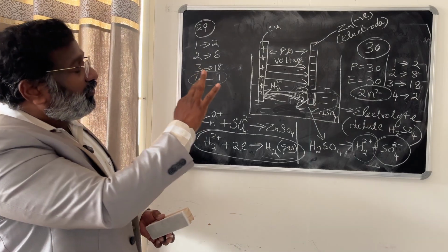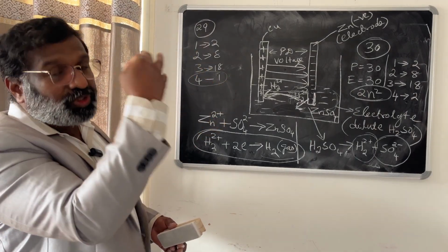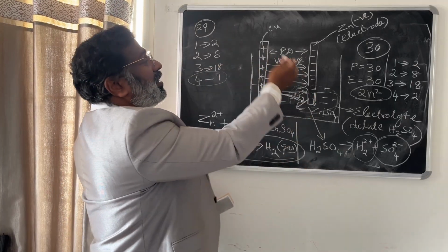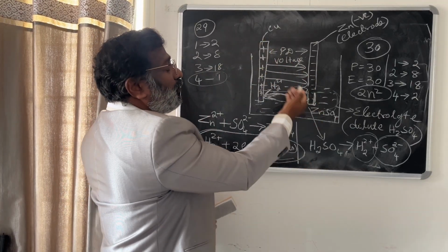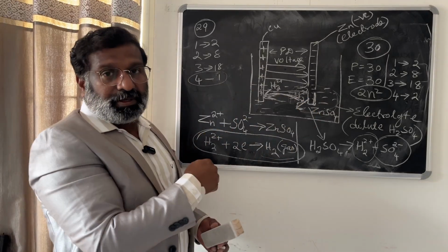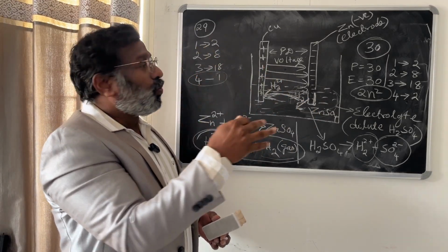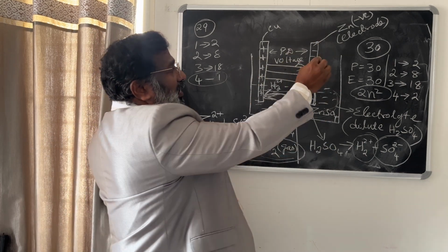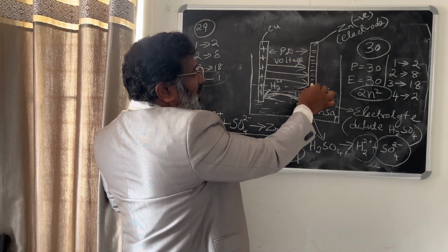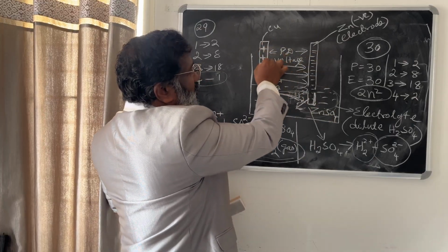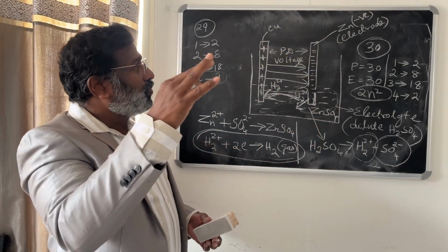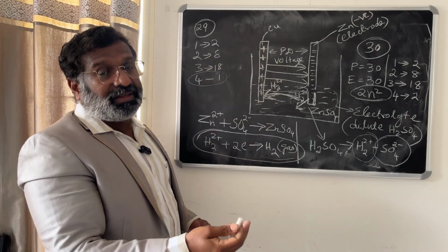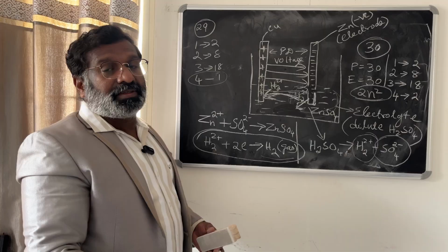So once the electric field is established, once the electric force comes into action, the chemical force has to do work against that electric force. Overcoming that electric force, it has to proceed with ion transfer. So the charging rate decreases. Once the electric field is set up, the charging rate decreases. And as the charge increases, more positive here and more negative here, as the amount of charge increases in zinc and copper, the electric field will also get strengthened. Electric force will also increase.